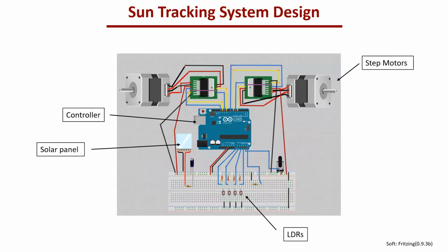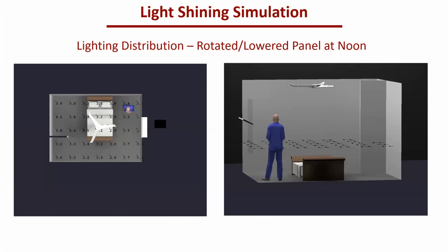So when you say you eyeballed it, did you look at those foot candle numbers and try to maximize this? What do you mean? No, in fact, I actually got slightly better numbers when I made it, because if you look at the angle of the shelf on the right hand image, it's about 30 degrees or so. You'll actually get a better light distribution if you're doing something closer to 40 to 45 degrees.